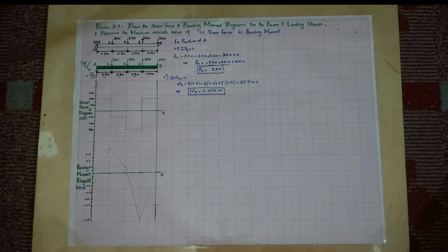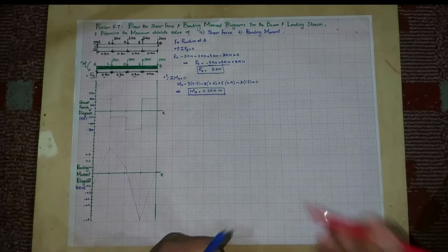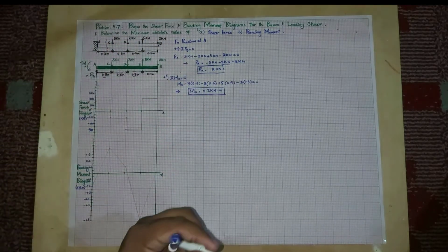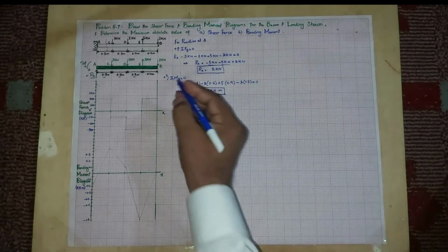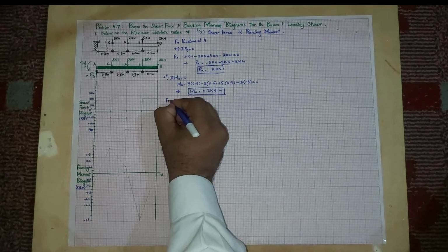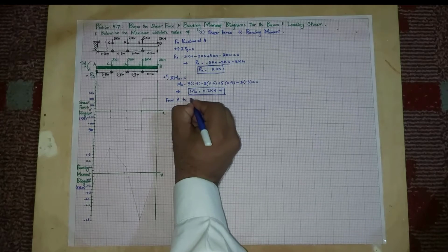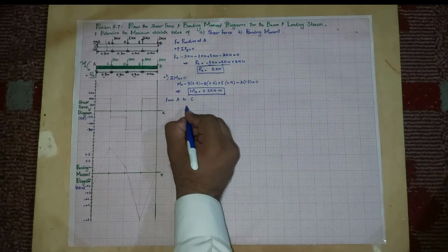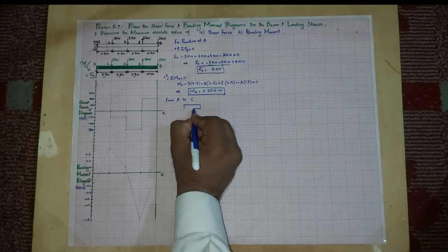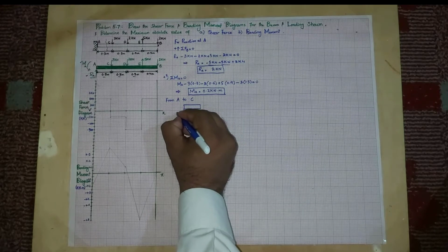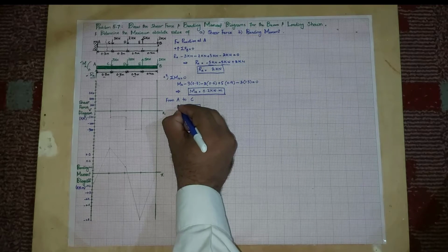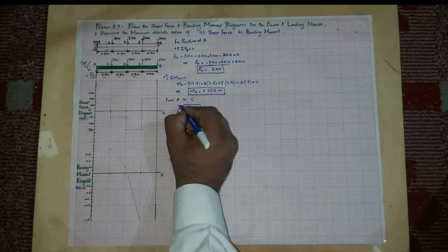We will move toward finding the bending moment equation and shear force equation, and then we will draw the bending moment and shear force diagrams. So let's start from the section moving from A to C. If we section it, the beam will be shown over here. There is a reaction force RA, and the moment MA, which is counterclockwise.